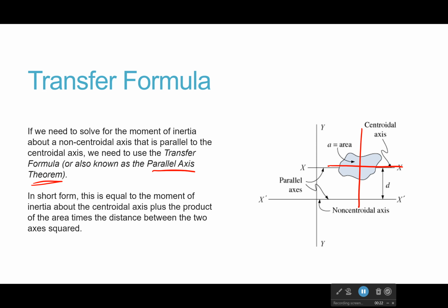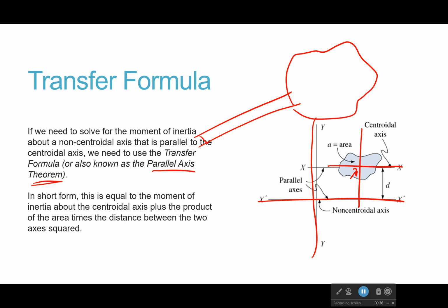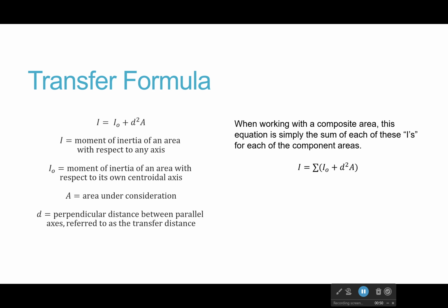It's just adding a correction term, saying, well, all those equations we had, they were for these two axes, but now I'm spinning around these two axes. And like I said earlier, if you have a shape on the end of a very long bar, it becomes much harder to turn if you're at least going around this axis. And so very, very similarly, you'll see that the moment of inertia will increase as we move away from our central axis.